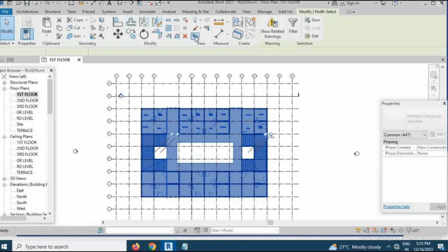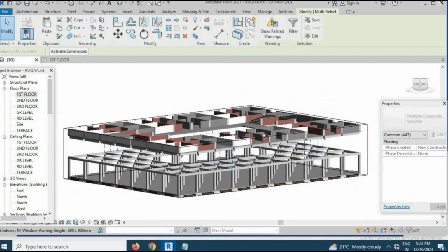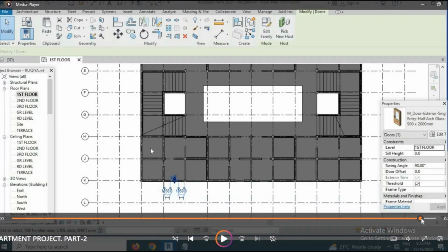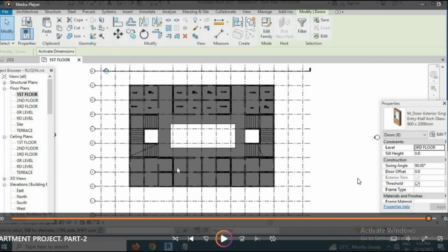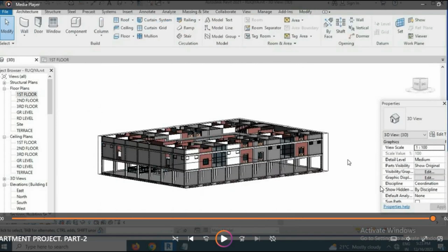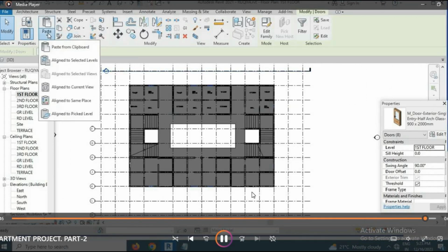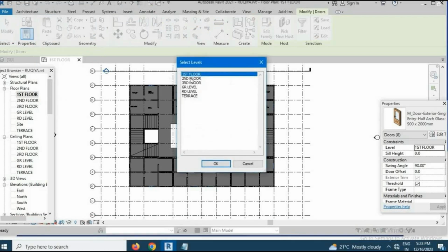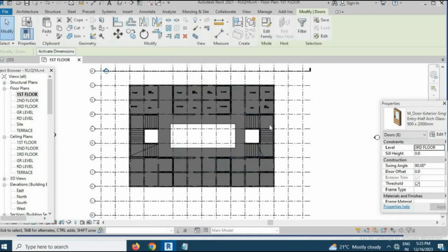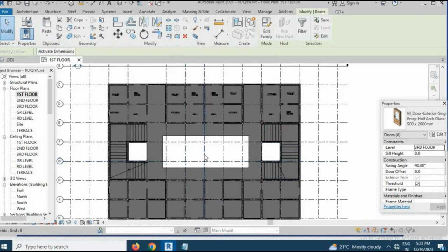Then select all the things, and then I'm going to see them in the selection box, and you can even press BX, as BX is the short form for selection box. Till here we have completed the curtain walls, texting, and doors and windows in this project video,